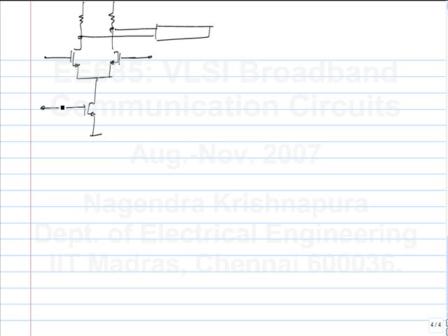Now if I want equalization, I want to add something to this, or I want to change the circuit in some way. One way I already showed was to add different taps, and each differential pair is driven by delayed voltages, delayed bits. Now I don't want to do that. I don't want to use flip flops. What are the other ways I could realize equalization?